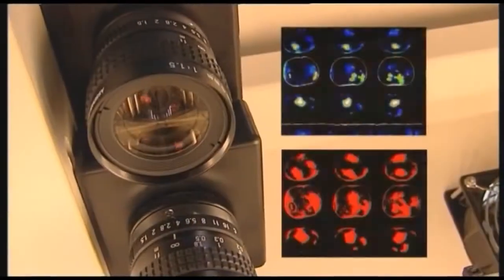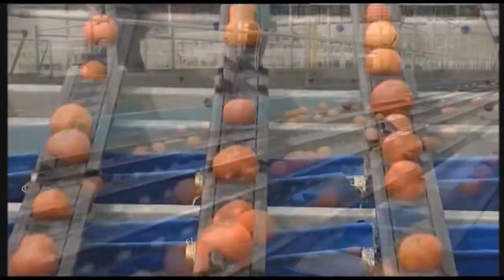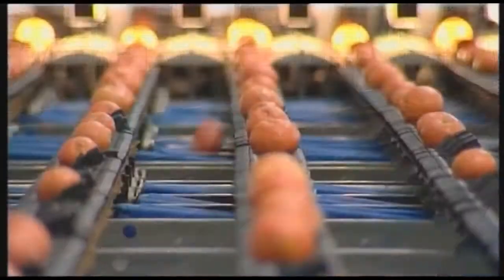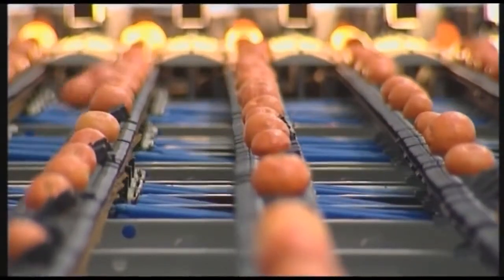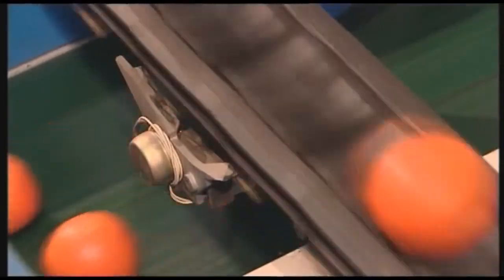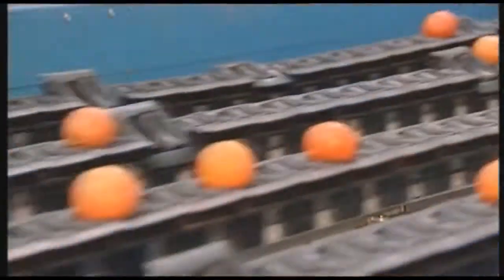Cameras perform multiple readings as the fruit spins, after which a computer sorts the fruit automatically. The Diablo-shaped supports then go through the weighing zone, where the loading cells are located and the corresponding weighing is performed. The readings are then sent to the computer, which synchronizes the passage of fruit with its unloading in the corresponding outlet. The sizer guides the different fruit sizes to the selection tables, where the product is reviewed once more before the conveyor belts send it to the selected packing.